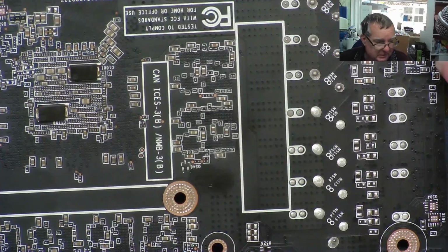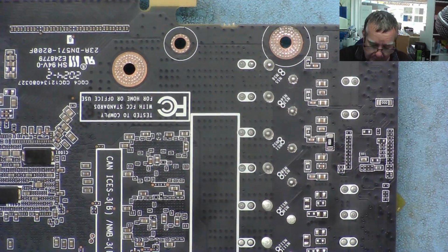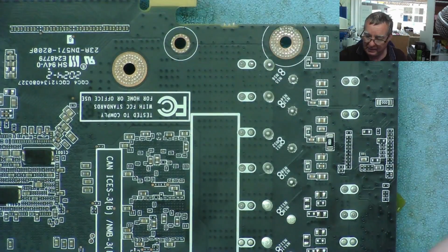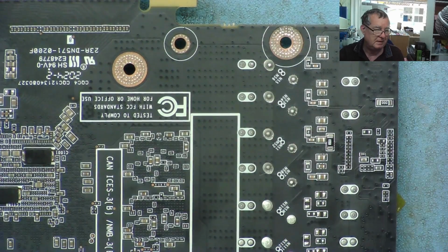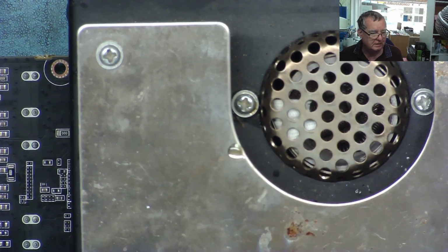The second point, as I just made then, is to use a preheater. So this is mine, you've seen this before, little Carder 853B. And this is a hot air preheater. You can see it just pushes hot air from underneath the PCB. So I'll get the board onto this and then we'll get this thing removed.